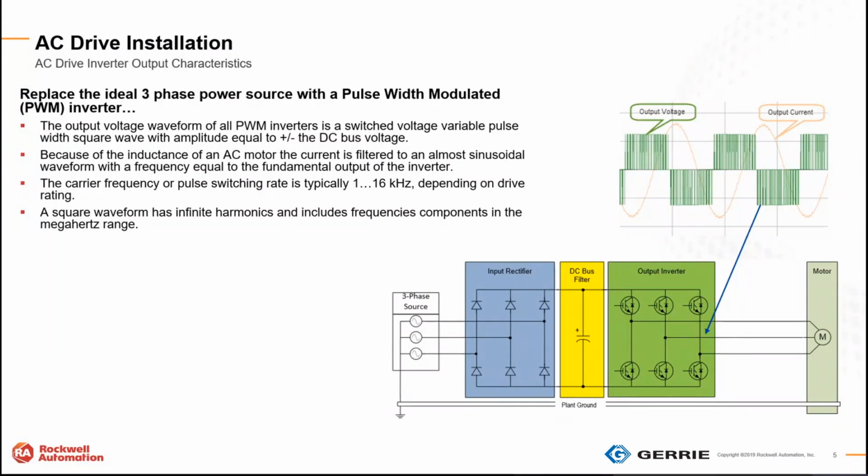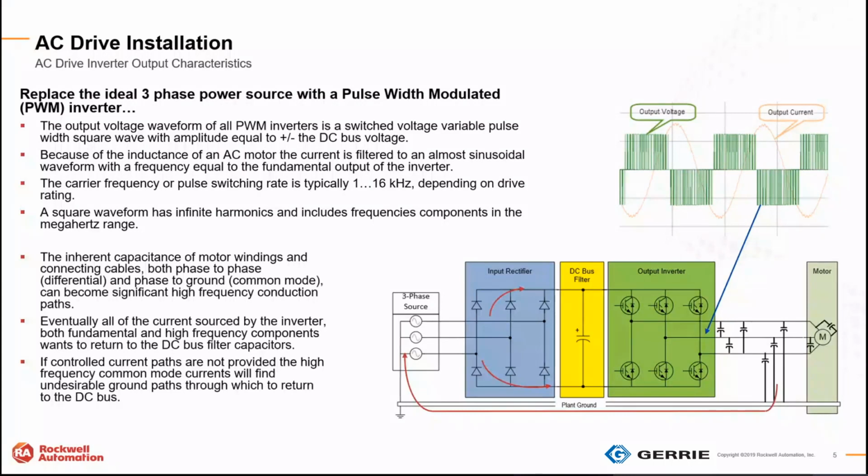The common mode noise, super high frequency, well above a harmonic frequency, is due to the PWM high frequency harmonics caused by that square notching. And all conductors have parasitic resistance, inductance, and most significantly capacitance between conductors and ground.